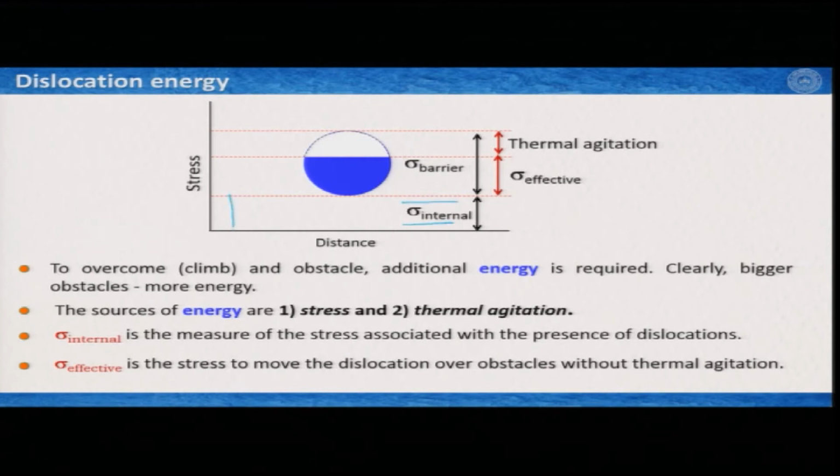So, it can give you a certain amount of stress to deform the crystal. However, if I have this circle here, this blue circle, as an obstacle, and a dislocation is moving this way, then it certainly cannot overcome this obstacle and come here to move further, to continue its movement.